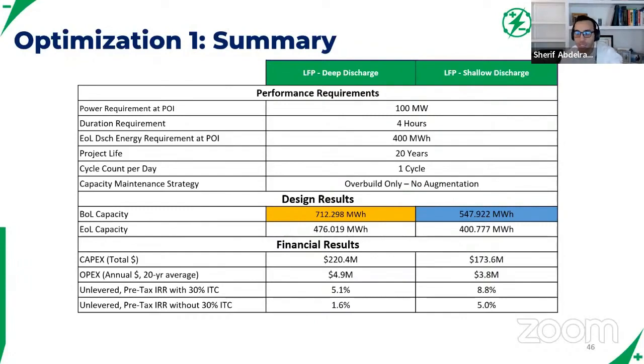Some of them have their standard, off the shelf, 1 cycle a day. In that case, they're assuming the worst case scenario. But in a lot of cases, they will say, give me a usage profile and I'll tell you exactly how much battery you need to purchase from me for this project to last 10, 15, or 20 years based on what you want. So I think that sophistication needs to expand in the industry. And I think it's going to come from developers competing and wanting to put together more cost-effective, reliable, and minimal risk projects.